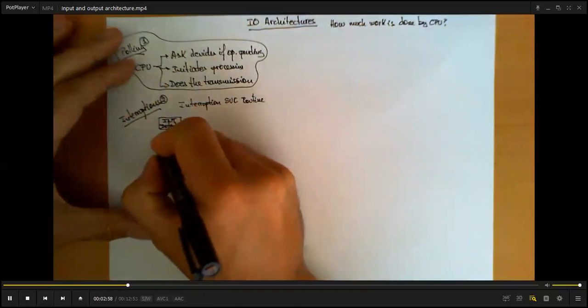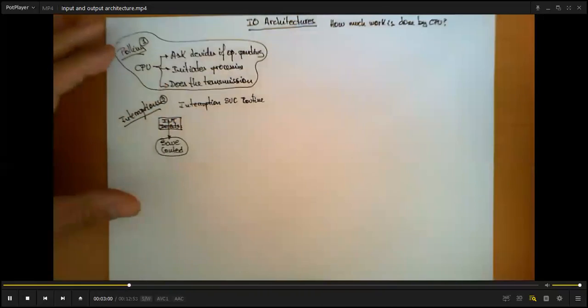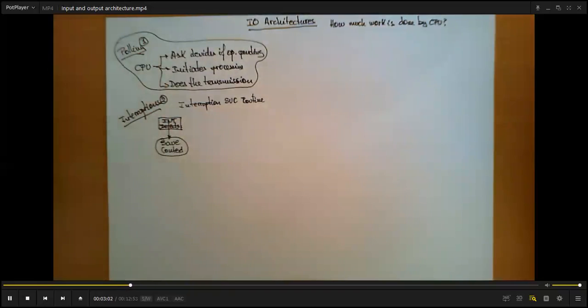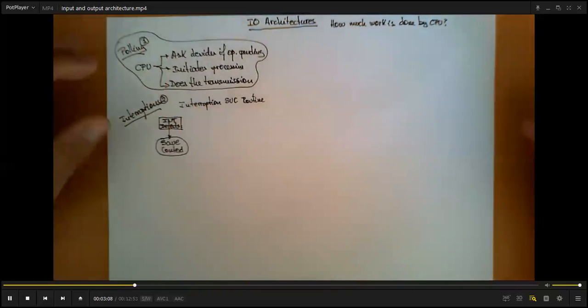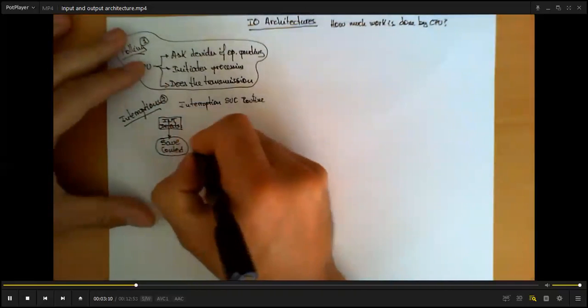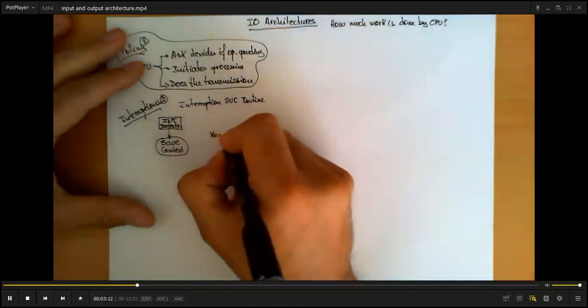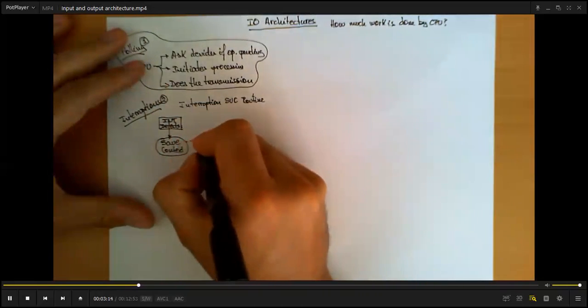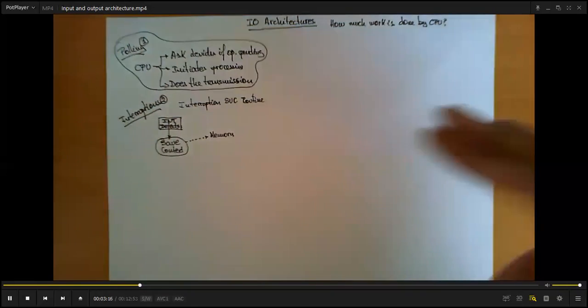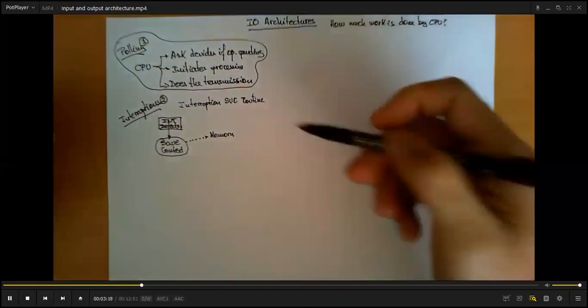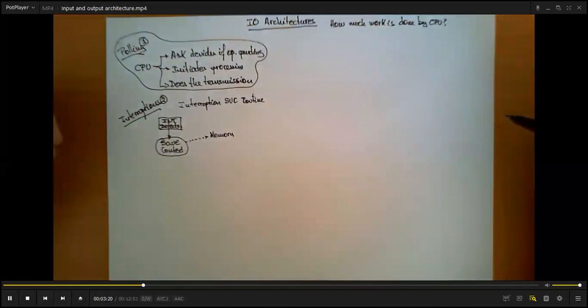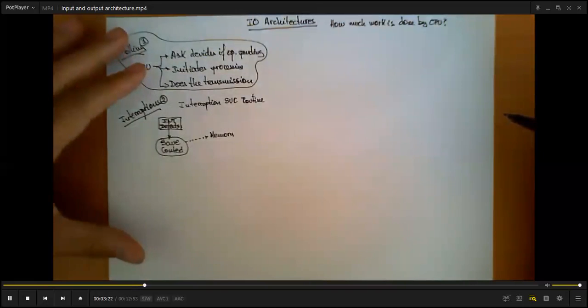This is because the CPU temporarily is going to use all of its internal resources like registers, internal flags, things like that, which are now going to be used by this interruption service routine. Therefore, we need to store a copy of this context in memory, so that we can restore the situation when we are done executing the interruption service routine, and the CPU can proceed executing the program normally.